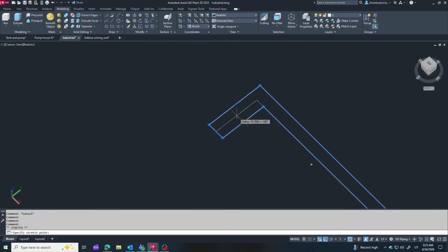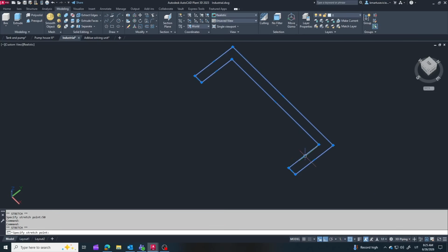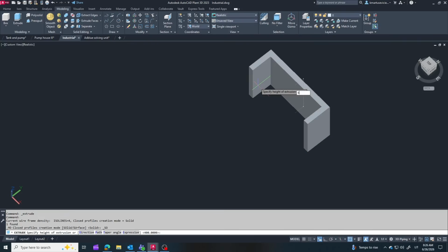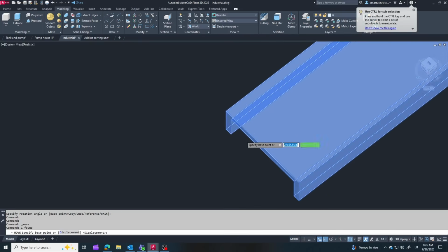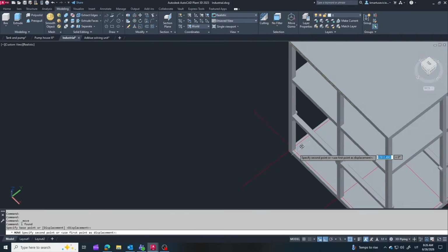I've had projects where I created an overly simplified building model. Later, when routing the piping, I discovered clashes with beams and floor slab edges, which meant going back and reworking the layout. That's why I prefer spending a little extra time on the structural model at the beginning. It helps avoid costly changes later in the project.